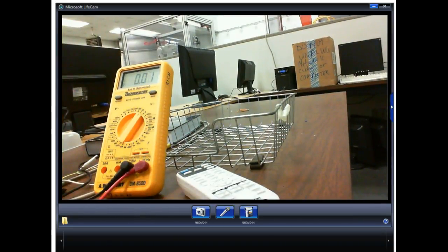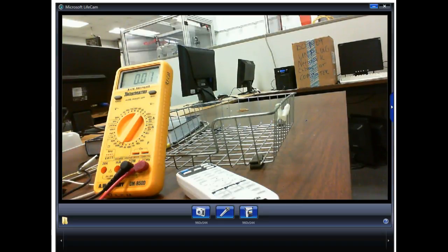So what's the first thing we're supposed to measure? Up at the top. So we're back up in table 39.2. So we need to measure VB. We're expecting what? 5.4. Okay, so here's our measurement. 4.8. Not too bad. 600 millivolts different.